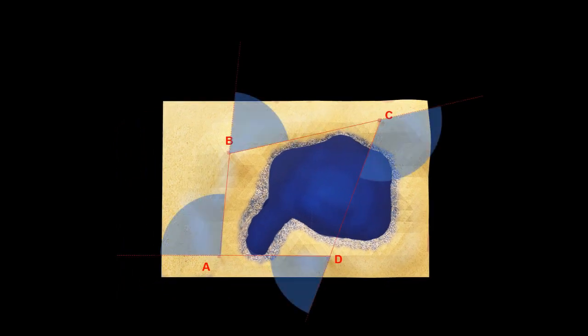Now, you can check for the accuracy of your traverse by simply adding up all the values of the deflection angles and see if the sum is equal to 360 degrees. So why 360 degrees? Imagine if we slowly take the traverse out of the picture while just retaining the angles. Let's see what will happen.